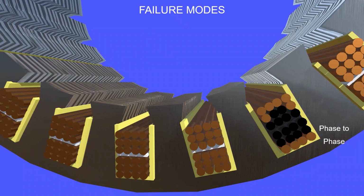A surge test can detect a fault between these as well as identify weakness in the turn-to-turn and phase-to-phase insulation. Remember, the resistance imbalance and inductive imbalance tests interrogate the turn insulation, however they do not find a weakness or fault unless a fault has already occurred. That is too late. We want to find turn insulation weakness prior to failing, when the motor is nearing end of life.